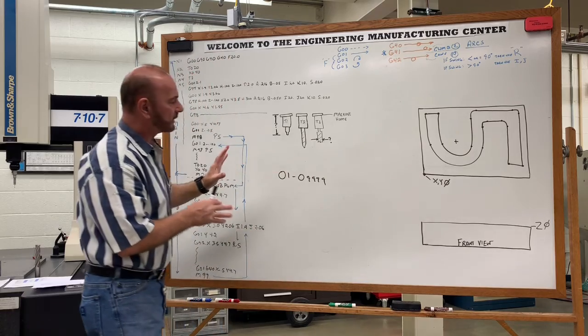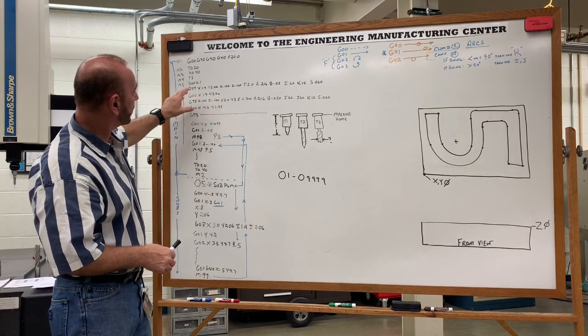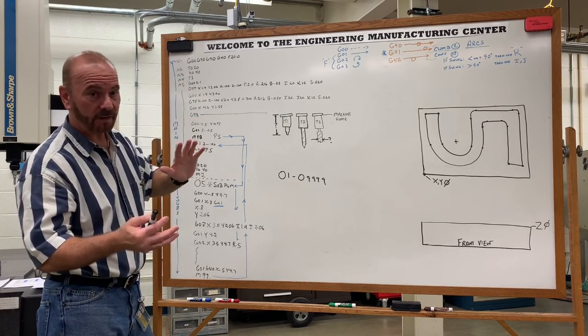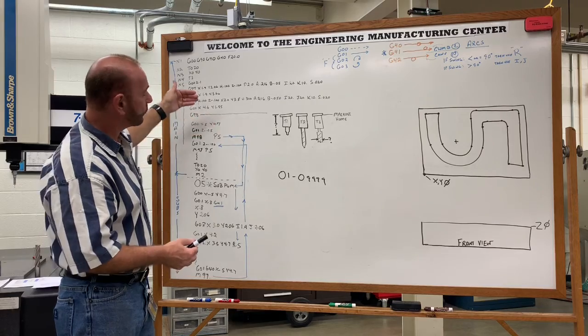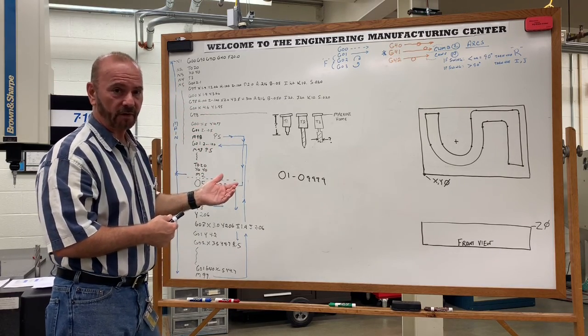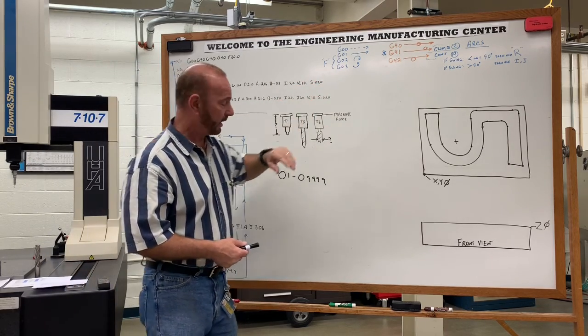So it's pretty simple to program, but that is the purpose of tool offsets and what happens when it calls a tool. What cancels a tool call out is another tool. So when tool 4 is called out or tool 5, it turns off the previous tool call out, just like the movement commands here also change that.